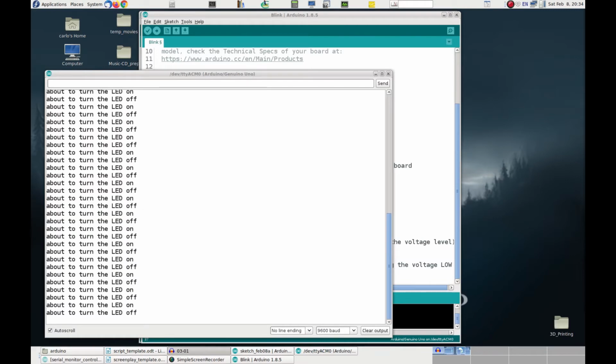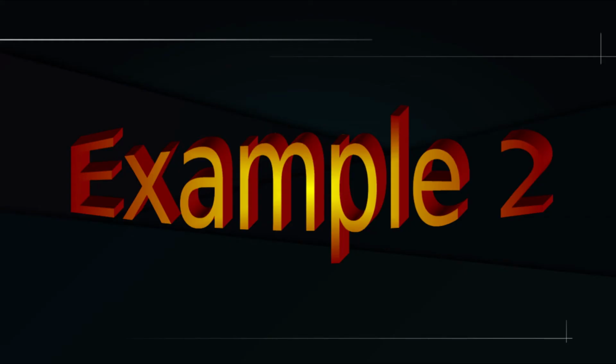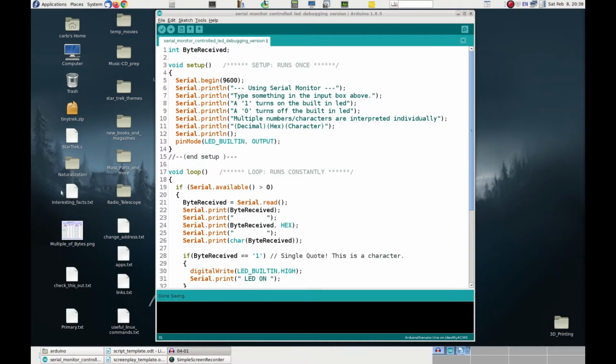For it, we use another program. We already saw that. It's the same one we used in the previous Arduino episode to learn about the serial monitor. Since this program already uses the serial monitor, the instruction Serial.begin is already here in the setup function, and so we don't need to add it again for our debugging purposes.